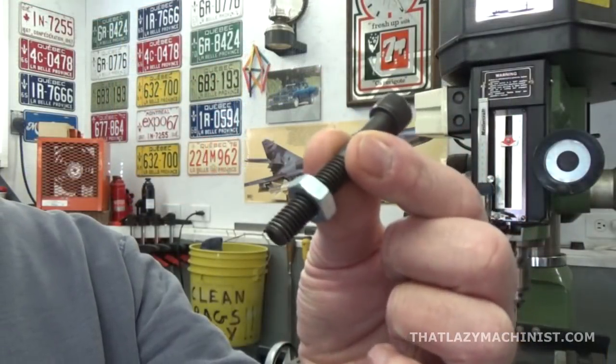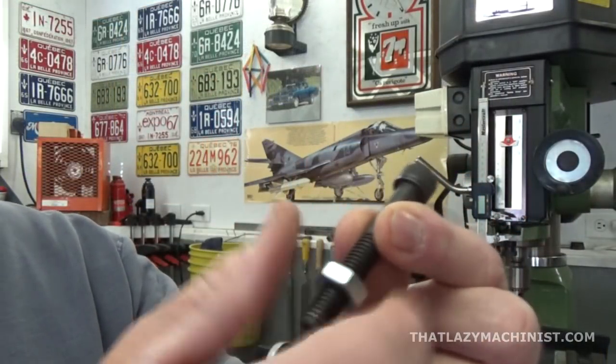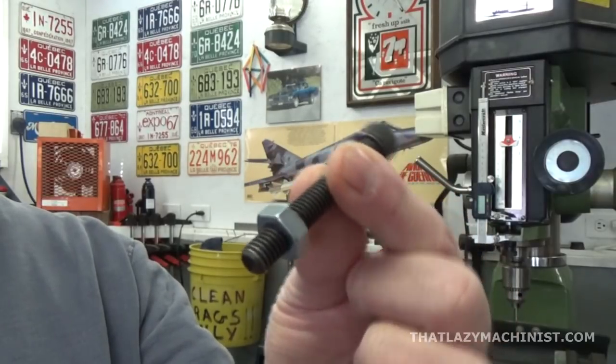Well, in a machine shop, there's 4 basic reasons for using a thread. And the first, well, is one that we're quite well acquainted with, and that's assembly. And we can see here a screw and nut assembly using a 60-degree V thread. Now, most assembly threads are 60-degree, but be careful. There's a few 55-degree threads kicking around out there.